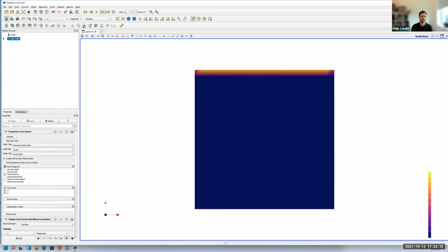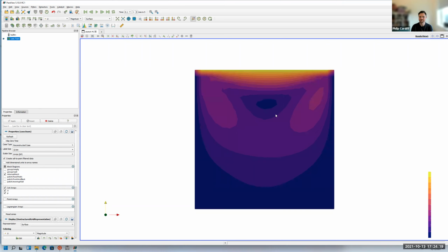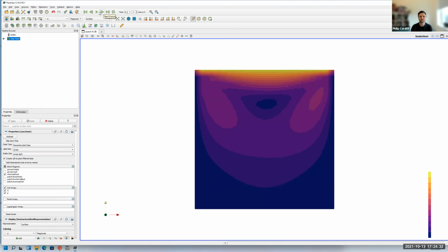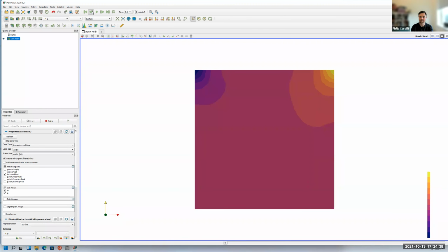So I'm going to go times U, and then if I skip forward, you'll see that there's some contours. This is the magnitude of velocity here. So I can skip around, and nothing really happens after 0.4, 0.3, 0.2, 0.1. Pretty much it's reached its steady state at 0.1. So 0.2, 3, 4, and 5 almost have the same results. You can look at P as well, and they're pretty similar settings.